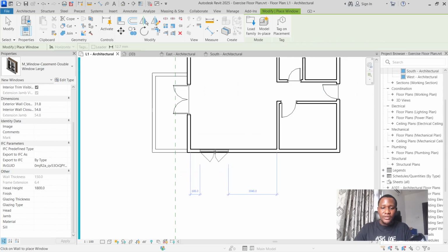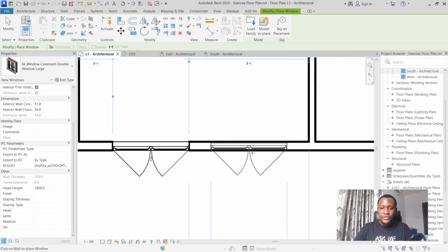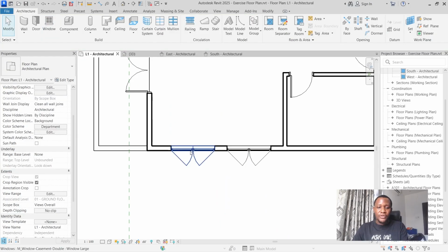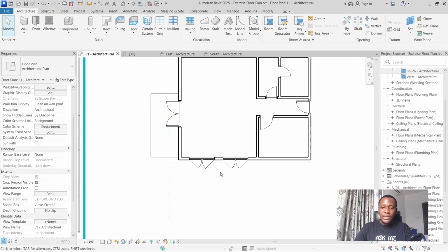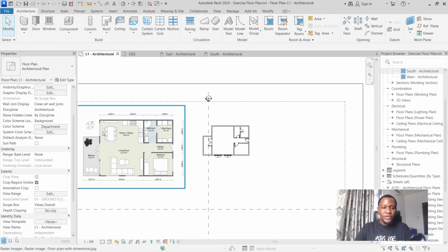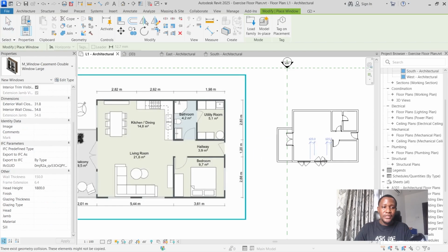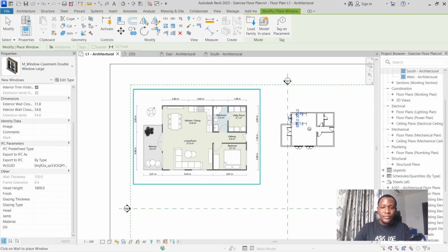We can use this. And let's just take a reference from our wall. Use this 800 from this side. It's 520 from this side, so we're going to have to move this other window a bit. Let's say 600 over here, and 600 from this other end. So that looks okay. And the next thing we're going to do is to put the other window on the other side. These windows are a lot bigger than the one that we're using. So let's go ahead and select window large, put it on this side. There we go. That's for the dining area.